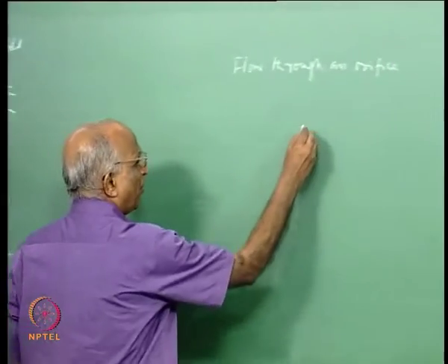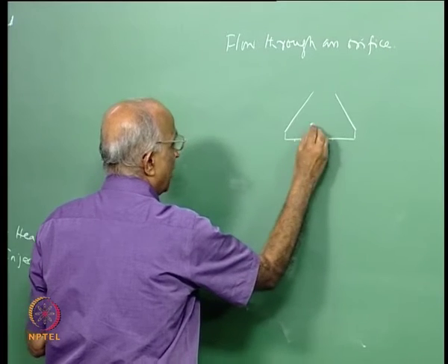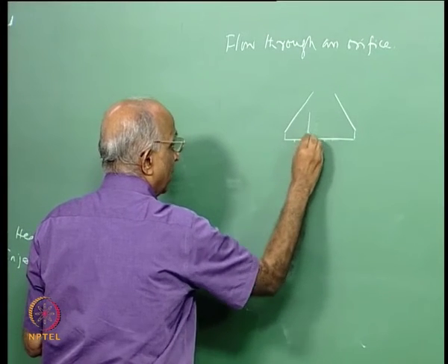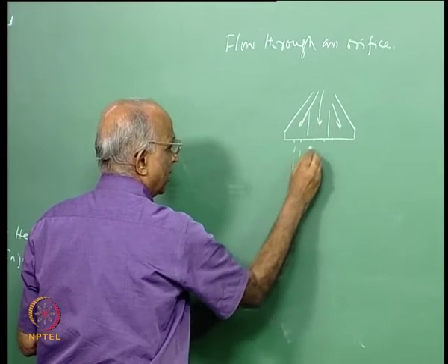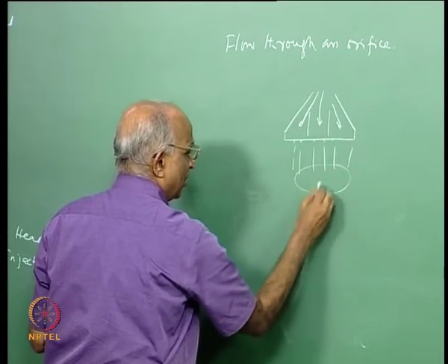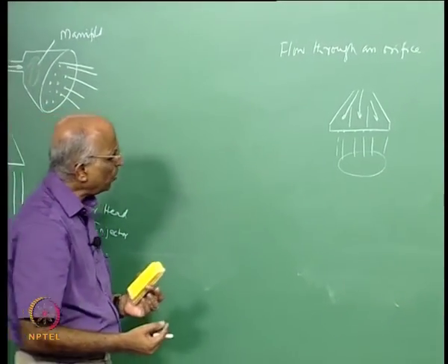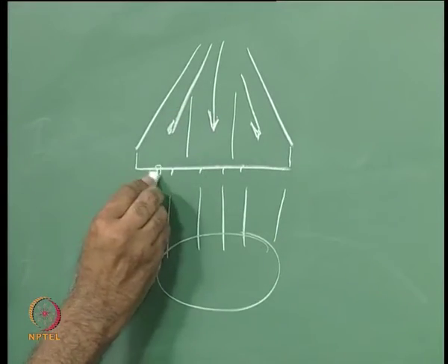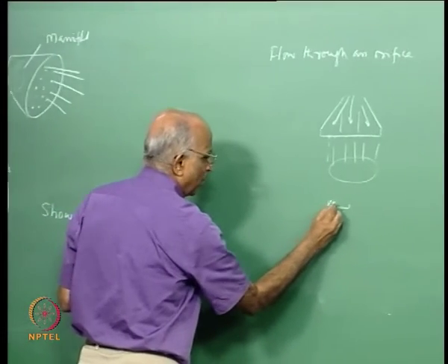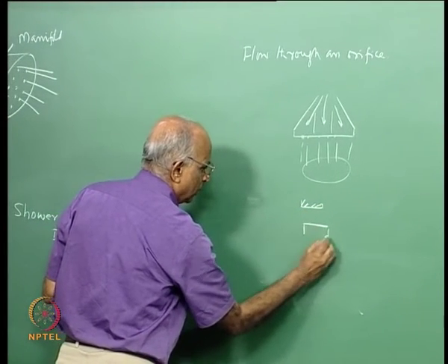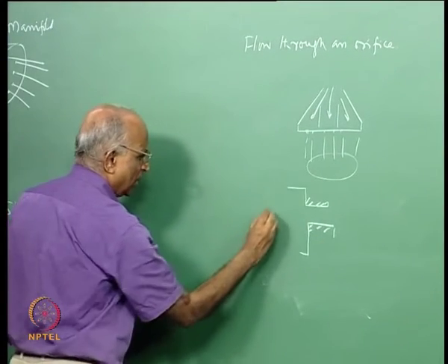But what we can do in a liquid propellant, you have the manifold here, you have the set of orifices here, maybe I could divide it, I could partition it in some way. In some region I admit the fuel, in some region I admit the oxidizer, maybe I admit them like this, I allow them to mix in this region and evaporate and burn. This becomes my showerhead injector. How do I find out the flow through the orifices? Let us say I now exaggerate one such hole, I say this is my hole over here, this is my manifold here, I have a lot of such holes, this is my manifold.